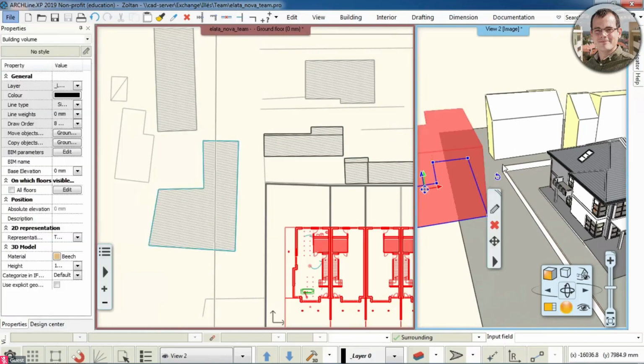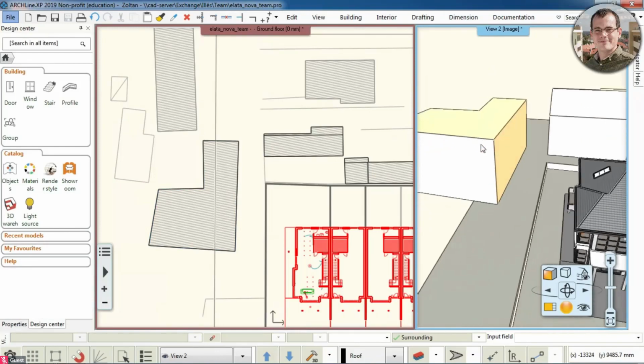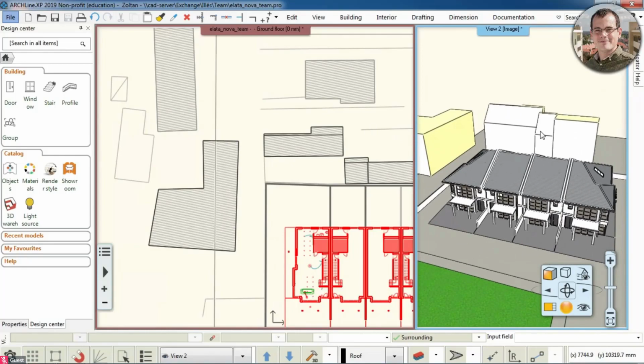But if I have something that I would like to pass over to you on a working area that you have, you can just log off for a while. I can make this change, and then you can log back in and take over the things that I just passed to your working area. Should you make any sort of mistake, it's not a problem. Just as you could move and copy things between floors or layers, you can do the same thing with the currently assigned item to one specific working area, and then change it back to the other working area.